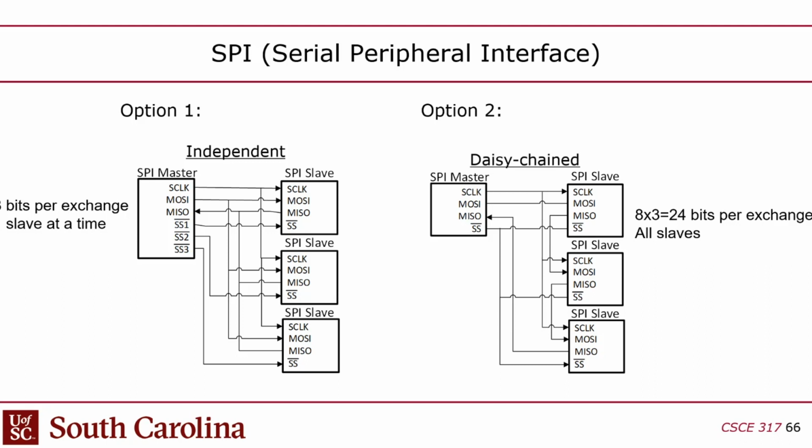And if you have an Arduino with I/O pins that you can use, the Arduino's hardwired SPI controller doesn't support this. So in order to get this to work on Arduino, I think you'd have to bit bang the SPI. You'd have to use software to do all the SPI. But anyway, the other issue here is that you can have more than one slave select, and then the clock and the MOSI will just go out to all the slaves.